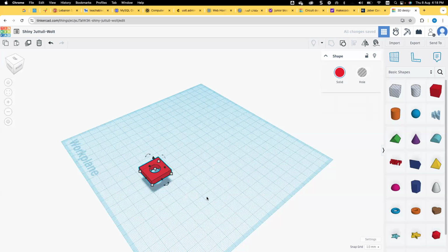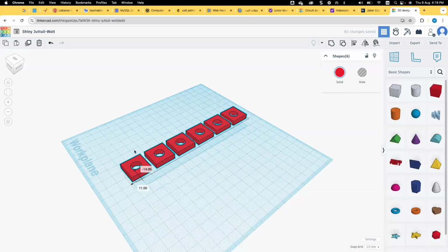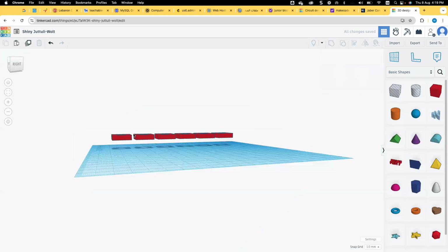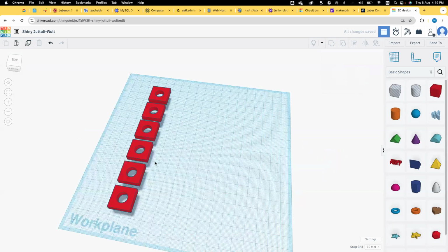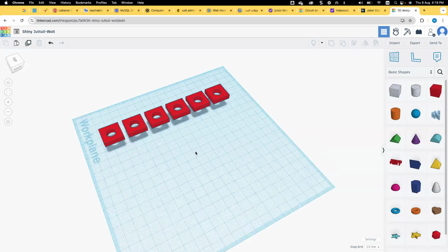And if I click on this object and I want to duplicate it, let's say 5 times or any number, I can click here on duplicate and repeat. So it's already duplicated on itself. So when I click using the left or right keys, I define the final position of the copied object. Then I click 1, 2, 3, and 4. I can select them all, and I can place them wherever I want. So here, I'm quite sure that all the objects are created with the same dimension, and the distance between them is the same.